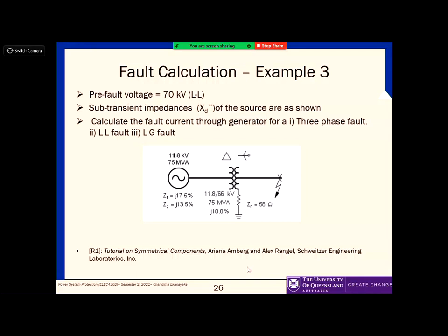But when you have these sort of circuits, now you can see the left-hand side is delta, right? If the delta is connected to 3 lines, can there be a zero sequence current flow in those 3 lines? What is the zero sequence? Zero sequence means current with the same phase.